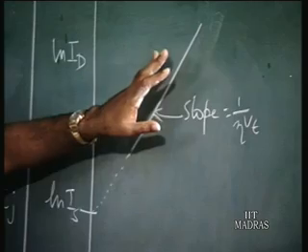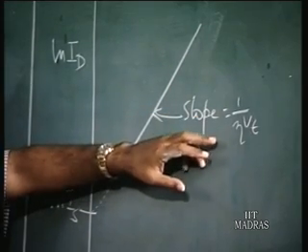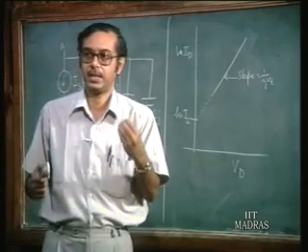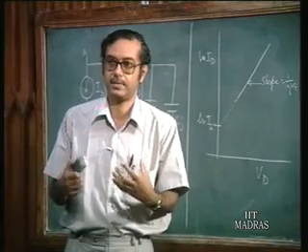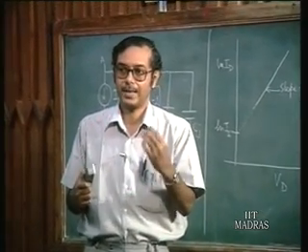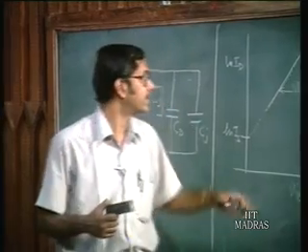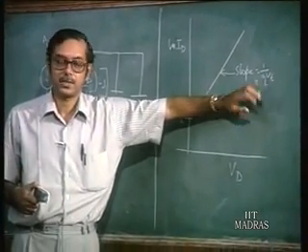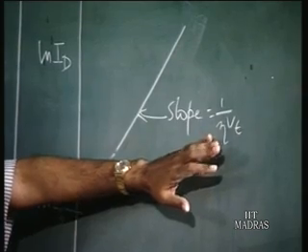It is very difficult actually to model the exact value of eta from the model, because this is due to some non-idealities, and one has to really know all these non-idealities in the device properly to get the exact value of eta from a model. So, it is usually extracted by doing the experiment. This value of eta usually lies between 1 and 2.